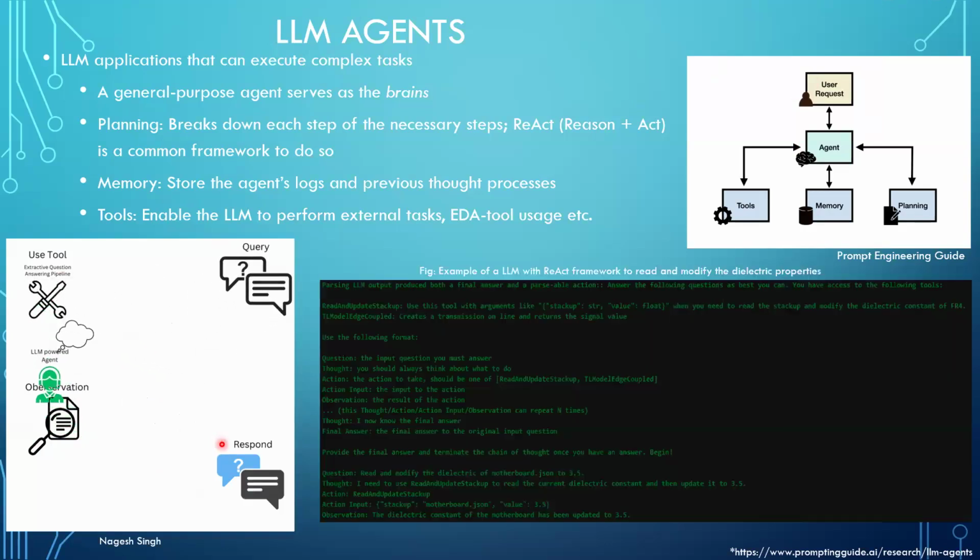So here is an example where we use the LLM again to exercise some of the tools. The exercise we ask the LLM to do is read the design spec to discover what the transmission line parameters look like. The first action it does is read through the transmission line parameters, right? And then the second step is, once you get the parameters, feed this transmission line geometry information into an API, where the API will initiate a simulator to do the simulation of a transmission line and give me the answer of what the structure looks like.